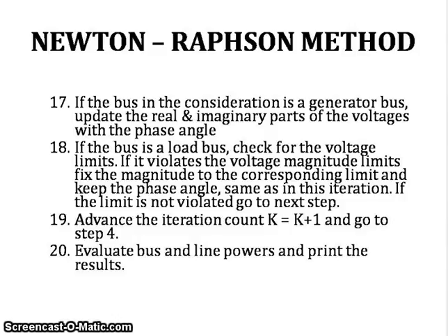So this would be the Newton-Raphson method, where we assume all the buses are PQ buses, and you have many nonlinear algebraic equations. We have vectors of residues, functions of voltage and angle.